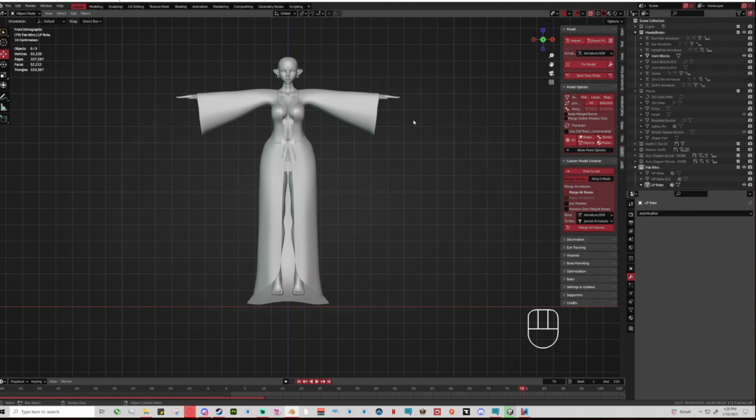I'm going to completely own up to it: my UV maps aren't always the cleanest, but you really want UV maps to be super clean if you want your customers to be able to edit things. For a t-shirt, you want the front separated from the sleeves and the back, so that if somebody goes into Photoshop and wants to add their logo onto the front of the shirt, they can easily slap that logo on, see where the front is, and move about their day. Versus if you have the front split in half, that's going to be a lot harder for them to add their logos.